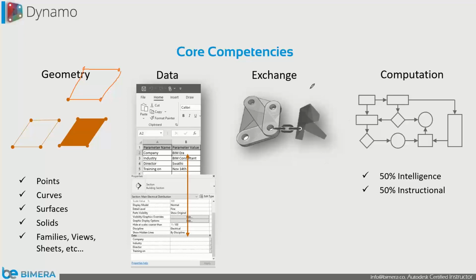Let's say I have one circle like this. Is it a cross section or a closed loop? Cross section. Very good, because it's not closed. When it comes to geometry, most people who are new to Dynamo confuse it here. They don't know whether it is a cross section or a closed loop. For cross sections there is a different terminology, and for closed loops there is a different terminology.